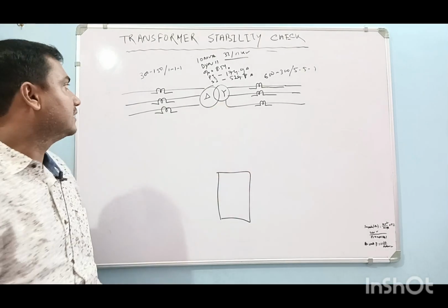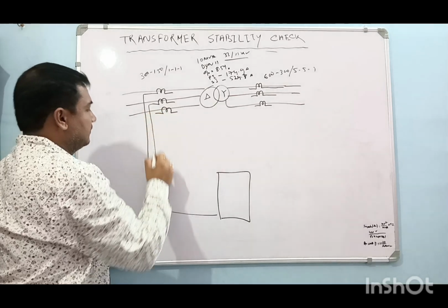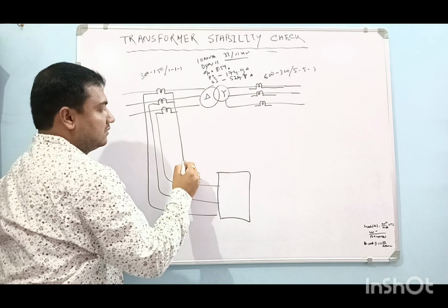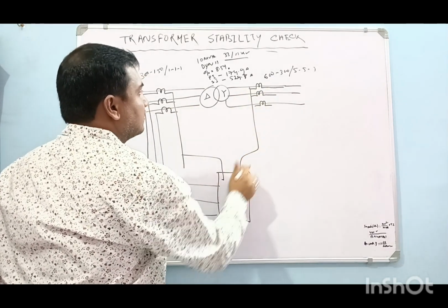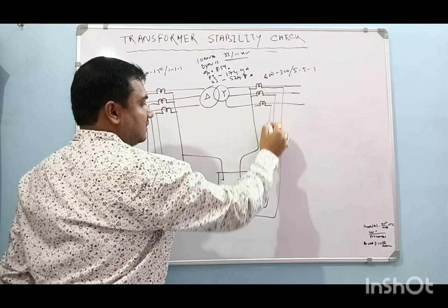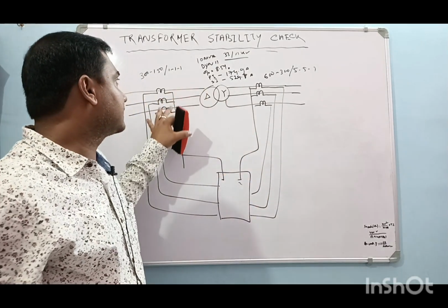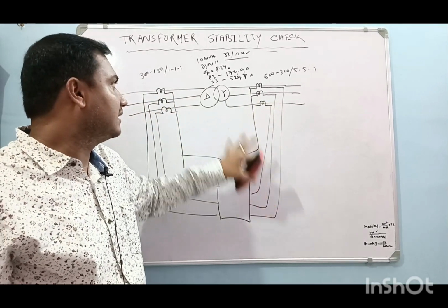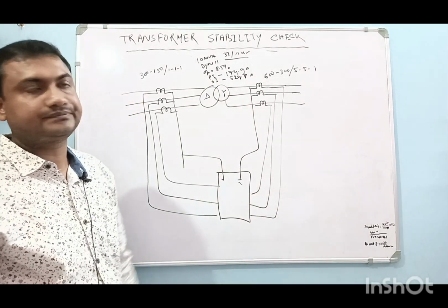That is the test. We are just completing the wiring. We have already discussed in my previous video how to do the differential protection relay circuit wiring, so I am not repeating the same in this video. So this is the differential protection relay. We have connected the HT side CT at 11 kV and we have put the transformer data and CT data in the relay.